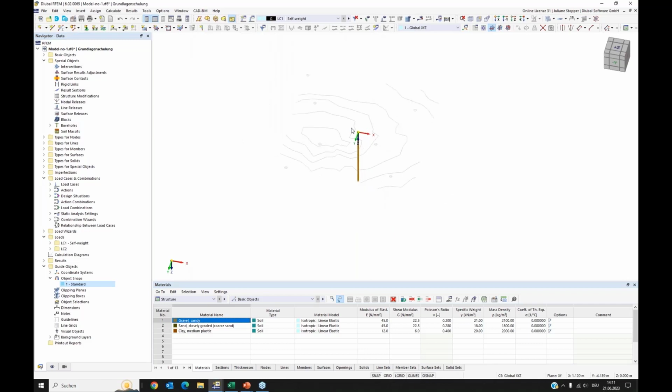Okay, now I can select this. Now I select like this. I have my borehole and this helping node selected. I press Control and I can move it to the place in my background layer in the graphic. And as you see, the last copy is always selected, so you directly can go on with copying with drag and drop.